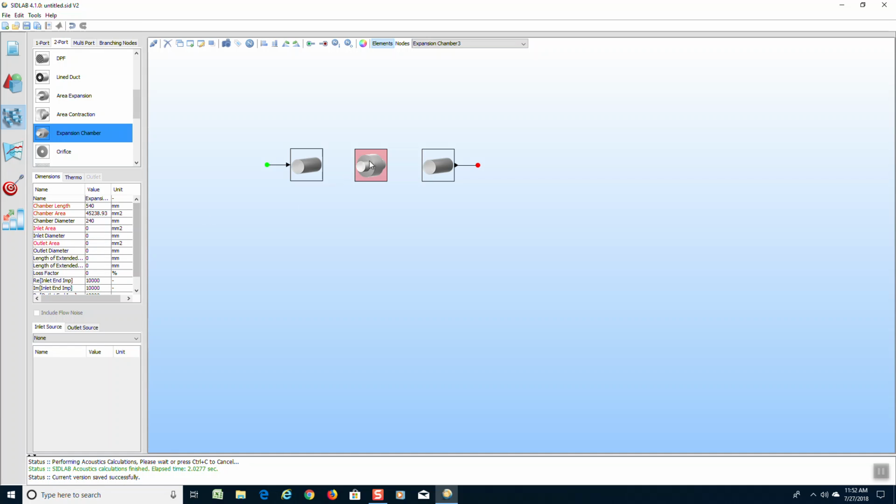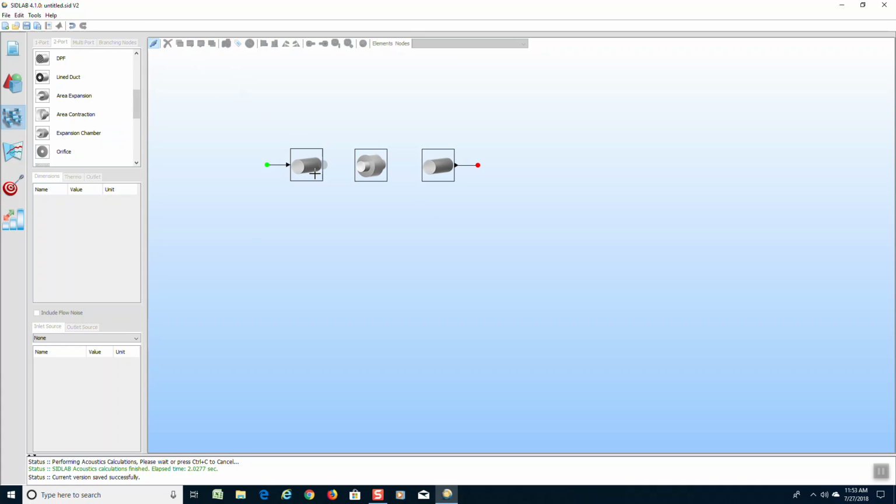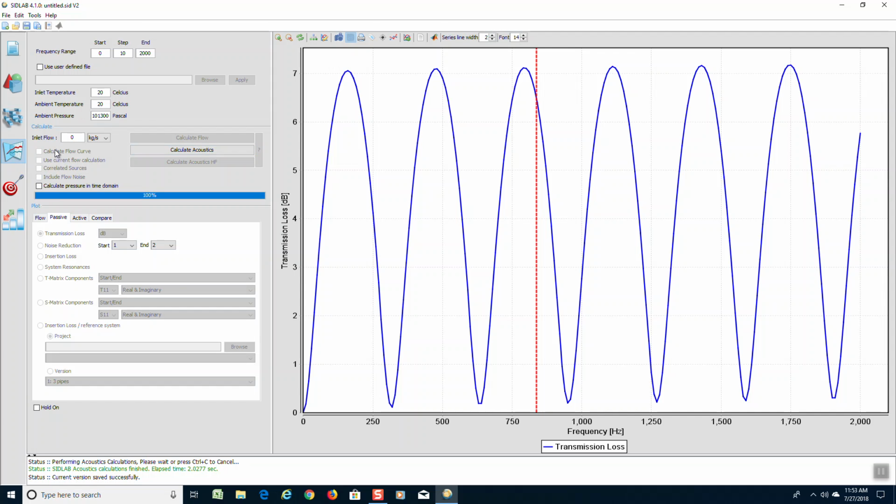And then it also is going to want an inlet and outlet pipe diameter, which is the same as these 2 pipes. So we will give it 116.5, and the outlet diameter of the same, 116.5. Now we have all the necessary information, there's sufficient information in order to solve this model. So we will connect as before. And now we are ready to run this model in the solution screen.